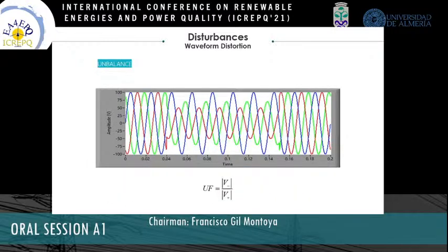The unbalance is also considered a power quality disturbance that occurs when the phases have different RMS magnitudes, or when the phase angle between each consecutive line is not equal, as is clear here between 0.04 seconds and 0.15 seconds. The main reason for unbalance is adding loads on a particular phase more than the others.